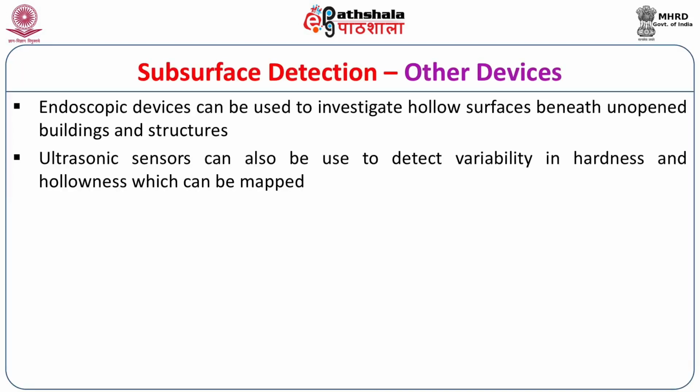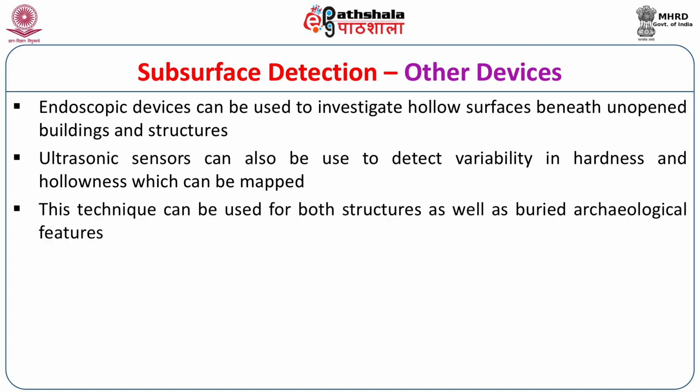Another kind of device that can be used is the ultrasonic sensor, which can be used to detect variability in hardness and hollowness, which can again be mapped. These ultrasonic sensors very easily detect the hollowness or hardness behind a wall surface or beneath a floor surface, which can be mapped, and a relative topography can be developed.